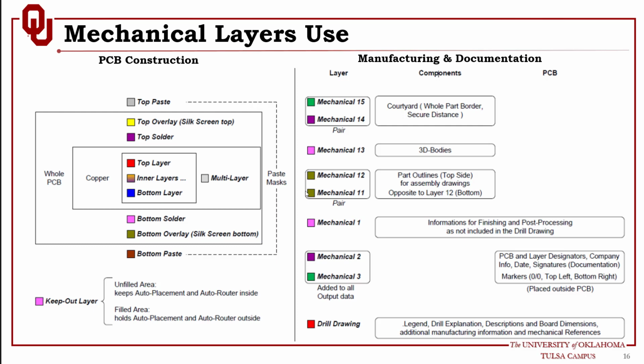So if your organization decided to use, let's say, mechanical layer 99 for the 3D model, all the components you create, or any engineer within the organization creates, should follow the mechanical layer standardization. If you create a component that uses mechanical layer 60 for the 3D model, and another engineer used a different mechanical layer, then there is inconsistency between these libraries.